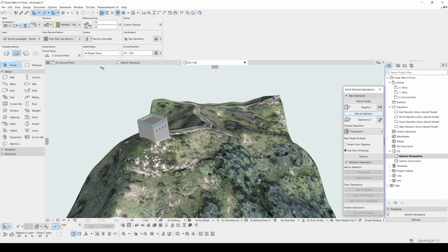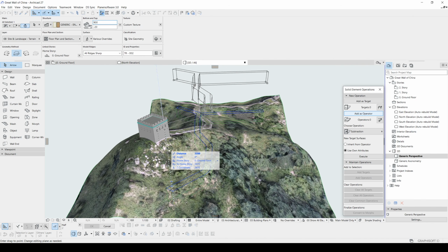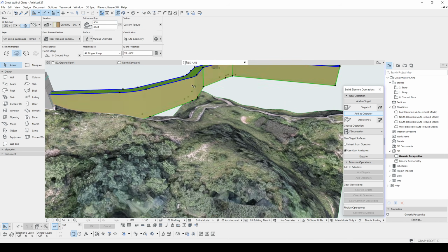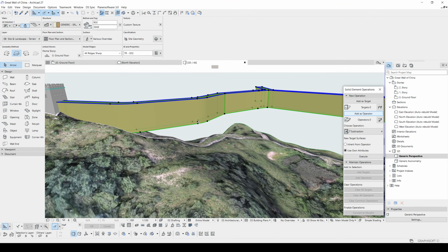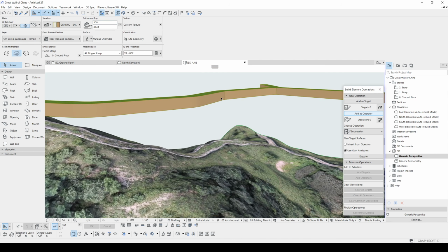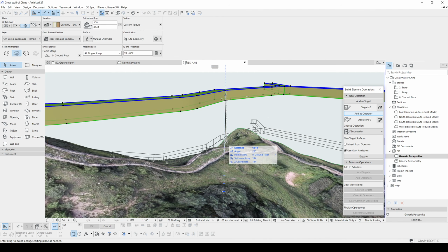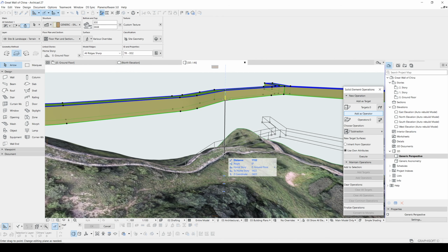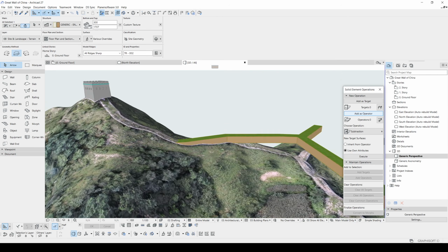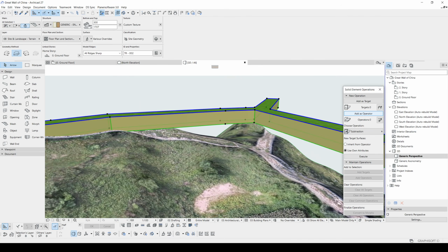Let's go back to 3D, and now we can change the thickness from here. This 20 is not important. The important part is this, which is 9 meters. After changing it, we will elevate this on the terrain to see all of the mesh. The visible part of the wall will be nearly 3 meters, so I will adjust this to 3 meters. And we are going to adjust this according to this point. This is going to be our starting position, adjusting position. We will continue from here.